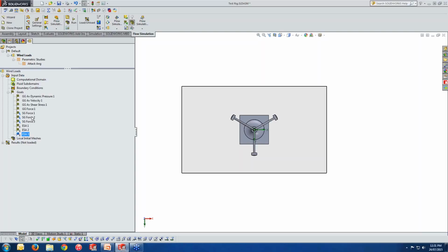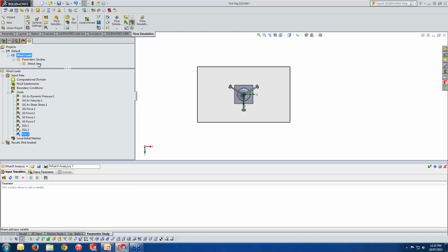However, this said, we are going to have different angles on this case study. Well, the whole antenna unit and structure is simply rotating from its position at 0 degrees up to 90 degrees. So what we need to do is very simple. You go into your project, right click and say, I would like to run a new parametric study.